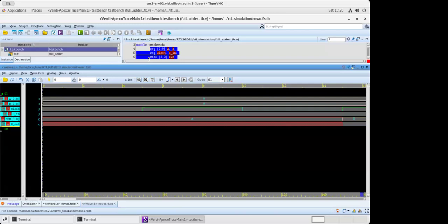Clock. So in your case, clock input is not coming. So do the same thing. Select the clock, right click, add to the waveform. It will give you the waveform, like, okay, there are two or three waveforms. Just select one waveform. It depends on how many pins you want, what inputs you want to be part of that. What about you?